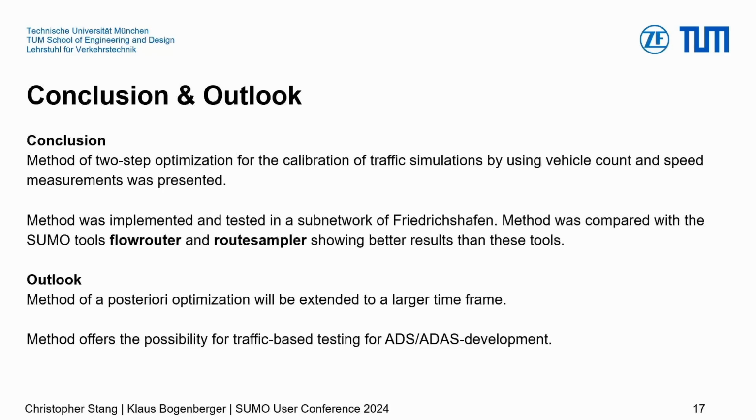Traffic-based testing is the counterpart of scenario-based testing, where you just focus on one specific scenario. Traffic-based testing means that you can investigate the traffic dynamic and also the change of the traffic dynamic if you want to develop any ADS or ADAS function. So if you want to investigate the impact of such developments, you can directly compare it with the reference that can be produced or generated with this method.